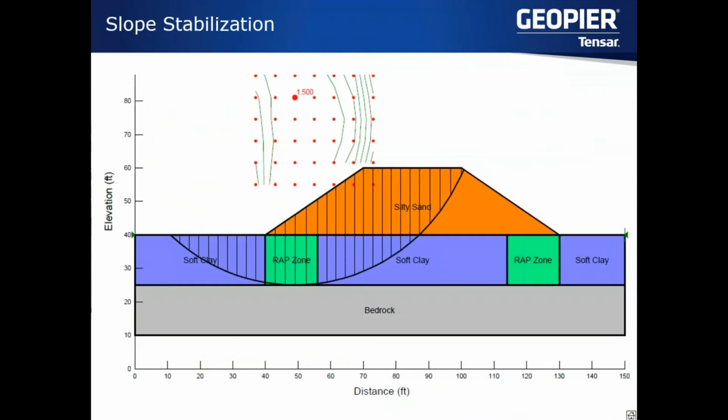So we talked some about, really exclusively focused on supporting structures and vertical loads. When we're talking about slope stabilization, we've been using ground improvements to improve global stability for some time now. That's essentially a process of improving the composite properties of the zone within the critical surface to improve the factor of safety against sliding.